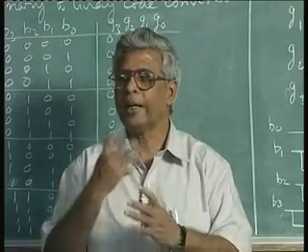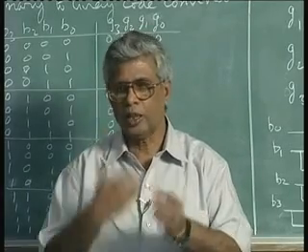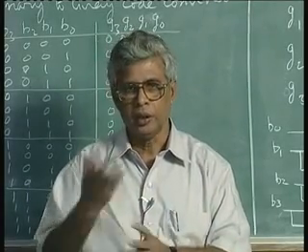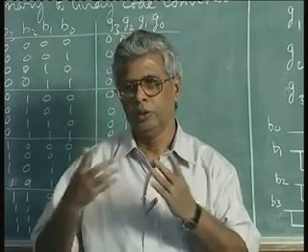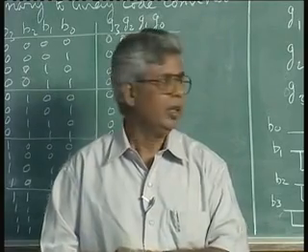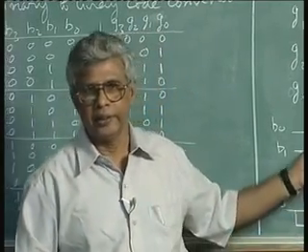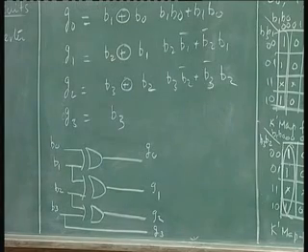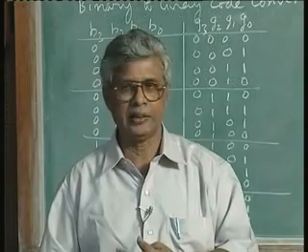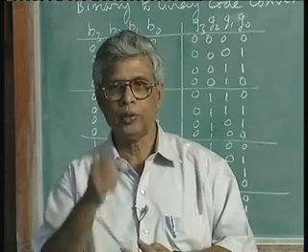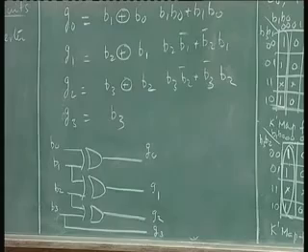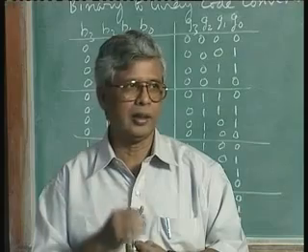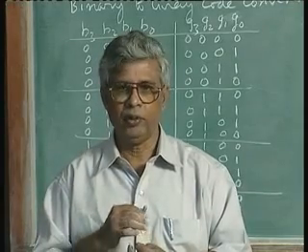Draw a functional block diagram. Write the truth table. Get the map. Do the simplification and draw the circuit. Get the gates. Go to the lab. Wire it. Measure it and test it. That is the simple design procedure of a digital system. And I showed you with 2 simple examples, which are practical examples. We'll see some more examples in the next lecture, and